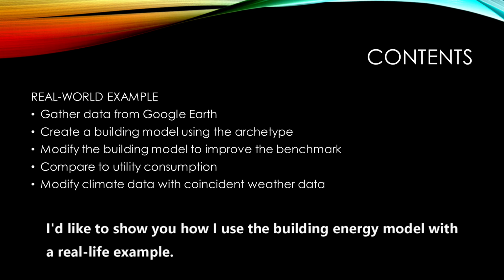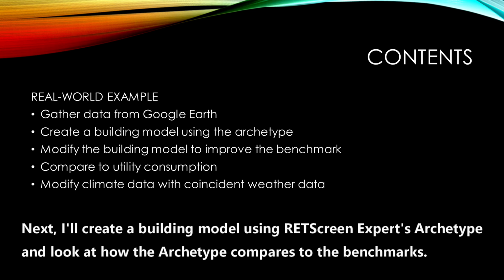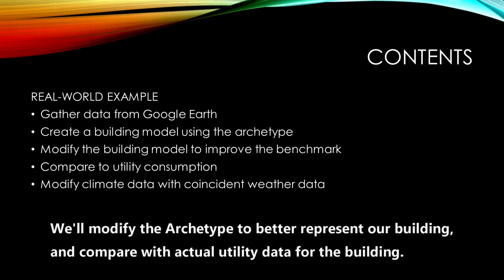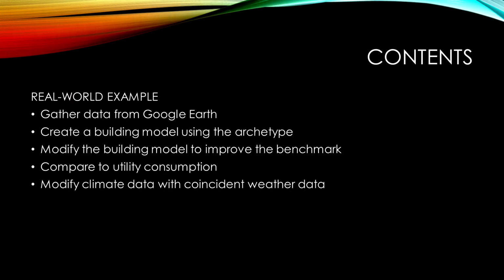I'd like to show you how I use the Building Energy Model with a real-life example. First, I'll gather some information using measurements in Google Earth Pro. Next, I'll create a building model using RETScreen Expert's Archetype and look at how the archetype compares to the benchmarks. We'll modify the archetype to better represent our building and compare with actual utility data for the building. Finally, we will modify the climate data with the weather data during the period covering the actual utility data.